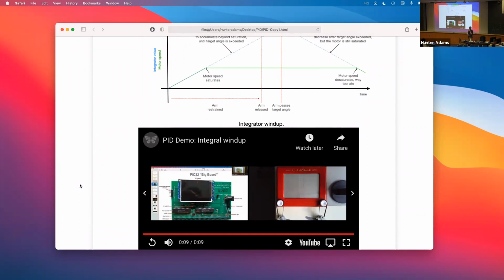Okay. And then to me, it seems like you would want to zero out or not take into account the integral term once you've reached a specific angle. So take into account the integral term and then disregard all the previous measurements once you've reached that angle, and then you can snap. Why am I still considering part of the integral term from an hour ago? I've been running this thing for an hour. So I agree with you.